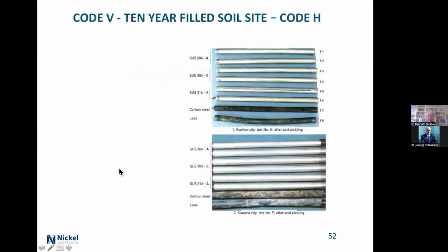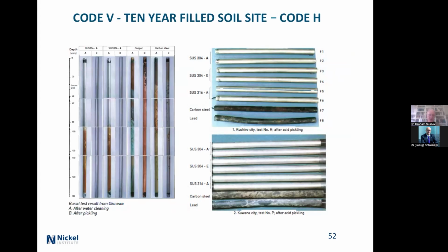This is stainless steel tested, actually it's stainless steel and carbon steel and lead and copper and all sorts of things. Tested for more than 10 years and pulled out. The stainless steels worked very well, except where they were driven in vertically, and you wound up with differential aeration effects down the bottom. But horizontal ones, yeah, you went down and they were better. If you came near the surface, then you got more of a surface thing because these were buried.